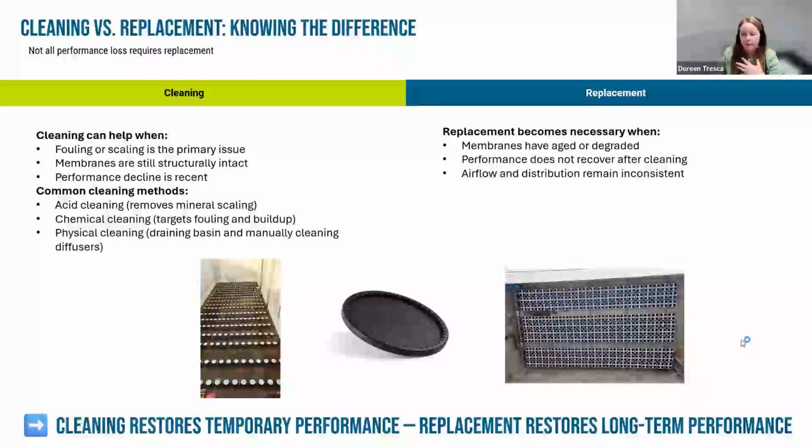It doesn't reverse some of the material aging that we talked about. Like the stretching, when the slits come apart, if the membrane splits, things like plasticizer loss. Cleaning the membrane is not going to reverse those things. When the membrane has degraded or when the performance does not recover after cleaning, replacement can become necessary.